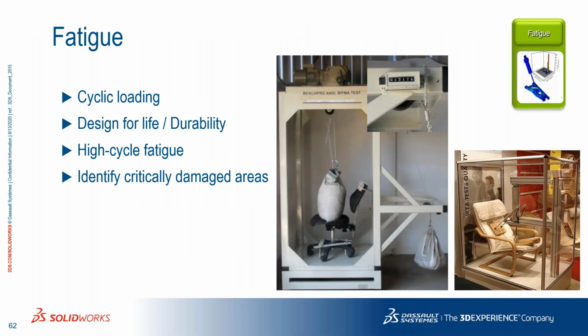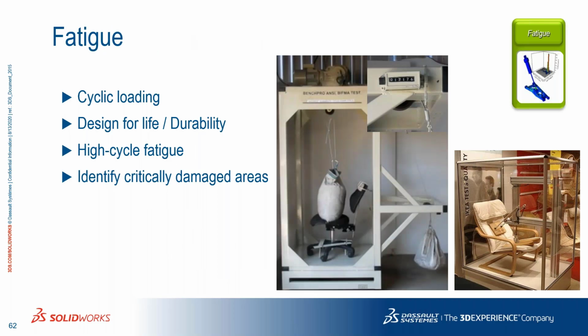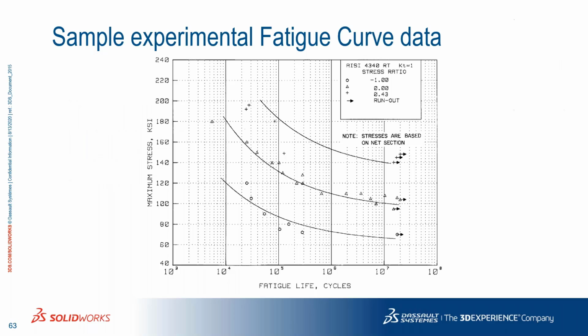Now, one more analysis we look for is the fatigue analysis. Fatigue analysis, in the sense, whenever you perform the analysis on any of the parts or assemblies, we apply the load only once, and we see that it might fail or it might not fail. In that case, we want to understand how long it is going to be available without any failure. In that case, fatigue analysis is very important. Sometimes it can take years of time to see, because as a manufacturer, we are going to give a warranty of say 1 year, 6 months, 3 months. So how will we get to know that? Using this fatigue analysis.